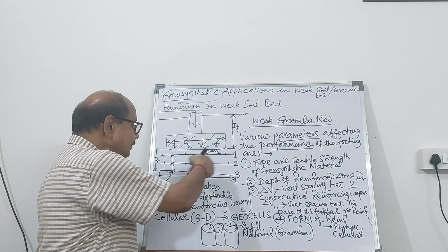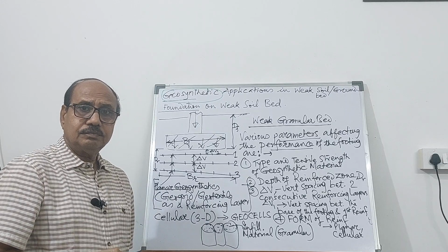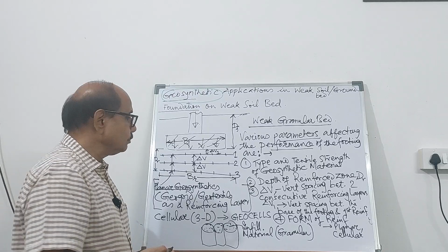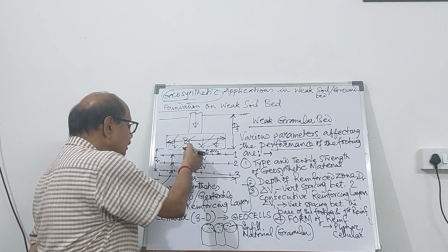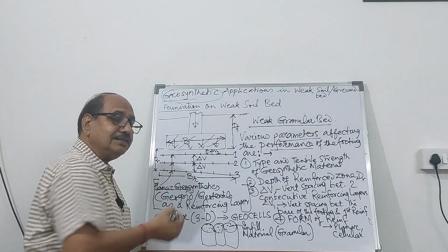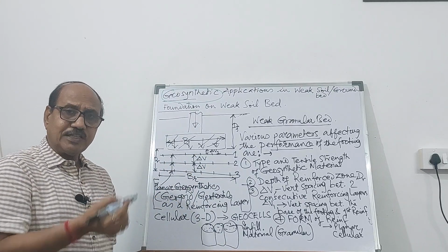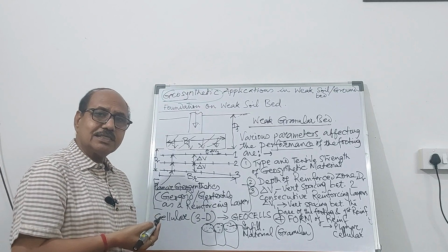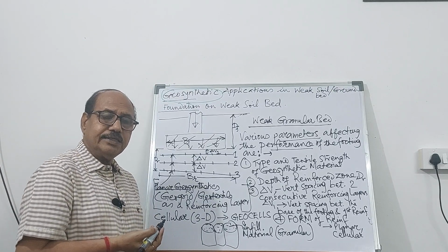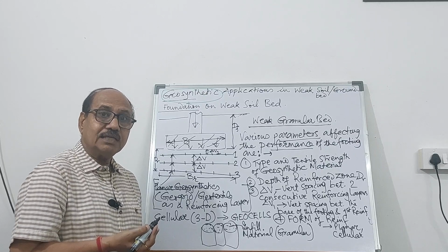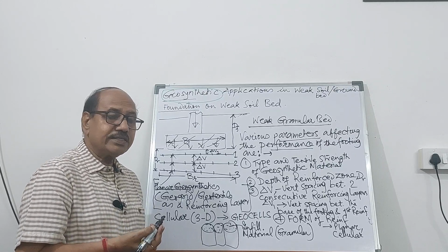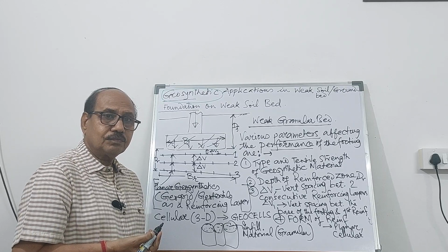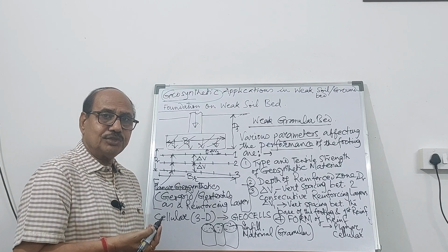What is the zone of influence, the zone in which the load is felt? So, the pressure bulb. We have learnt about this in geotechnical engineering by applying Boussinesq's or Westergaard's theory for stress distribution.